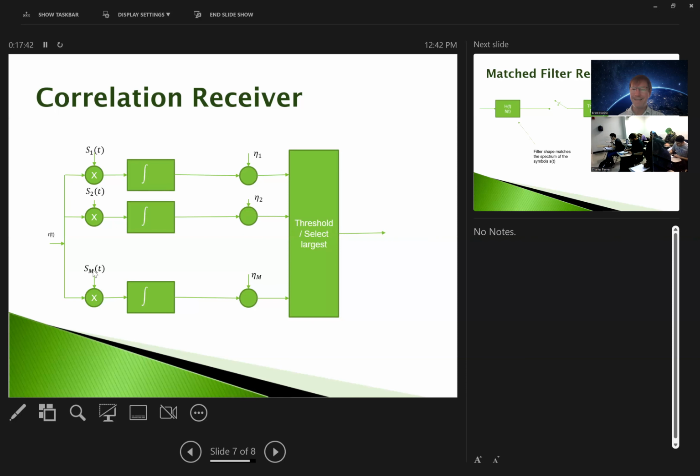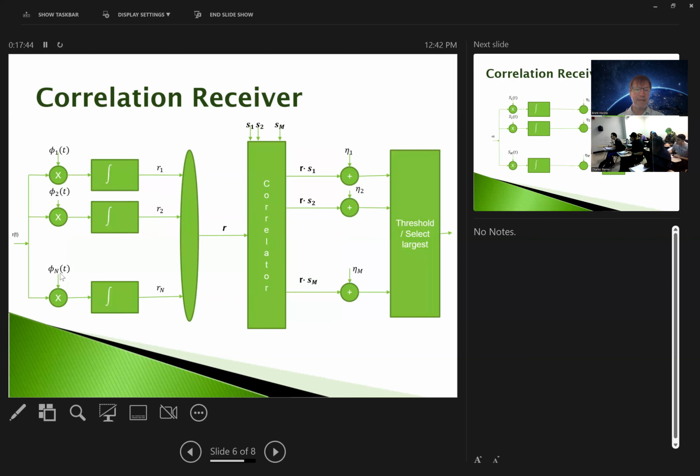It really depends on the size of M and the size of N here, right? So we have 1 to M here, we have 1 to N there. So one may or may not be larger. It depends on these basis functions, the set of basis functions required to accurately represent this time domain signal as a vector, versus your constellation size.